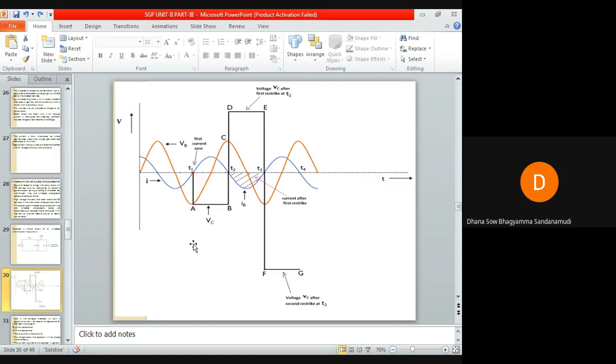The energy stored in the capacitor to be dissipated during such arcs is quite large, and the interrupter may get damaged in the process after restrike. Hence, the circuit breakers used for capacitor duty should be restrike free, and it should have adequate rating of capacitive current switching. Okay, usually vacuum circuit breakers, SF6 circuit breakers, or air blast circuit breakers are used for interruption of capacitive currents.